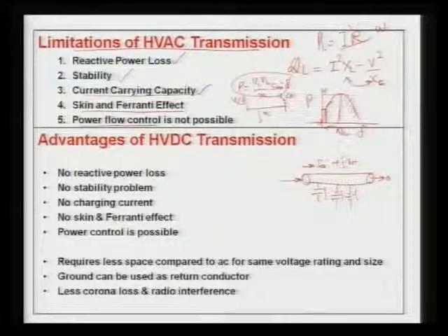That's why, as I mentioned, going for a cable longer than 50 kilometers is very costly. Earlier it was not possible; now it is possible, but it is not very feasible, and it is better to go for the DC system.